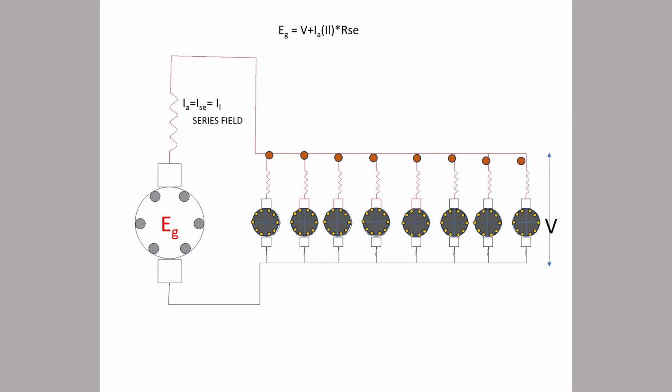Now here you see what is a DC series motor. I have shown you the DC series motor in the load. In a locomotive there are maximum 6 DC series motors in the Indian system. I have shown it here, 6 in number, and another is the source of DC power. The source of DC power in a traction system is the single phase